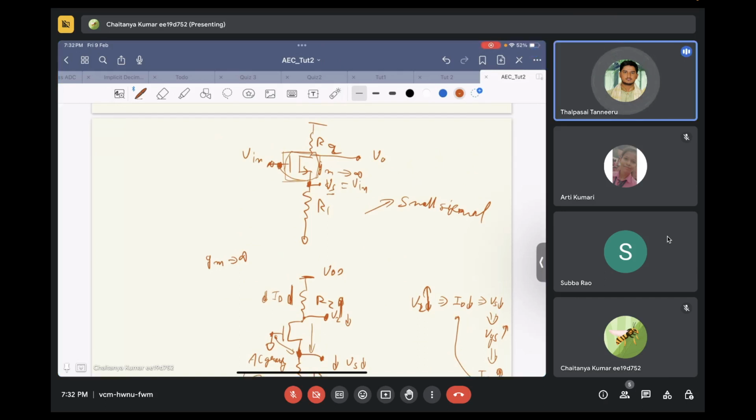How would it be possible, sir? This circuit is a negative feedback, and it will make sure that this happens. Okay, the circuit is in negative feedback, and the transconductance of this transistor is infinite, so the circuit will make sure that this happens. Otherwise, your current will blow up. In a negative feedback circuit, if you give a bounded input, you have to get a bounded output. Current can't blow up. So VS will be equal to Vin.